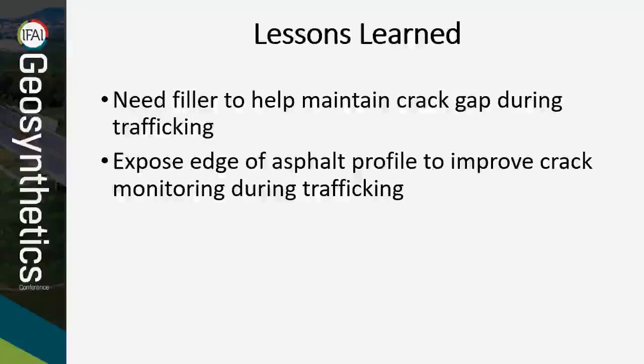Second, the edge of the pavement should be exposed to more easily see crack progression as a function of traffic, as the visibility of surface cracks is difficult to see, and progression of crack growth would be more informative.